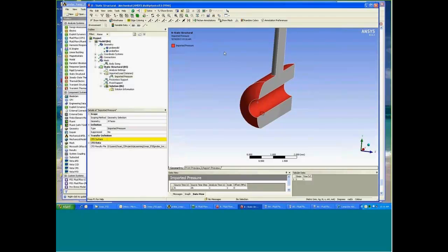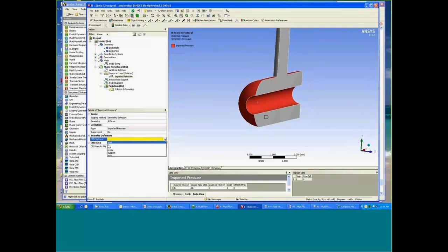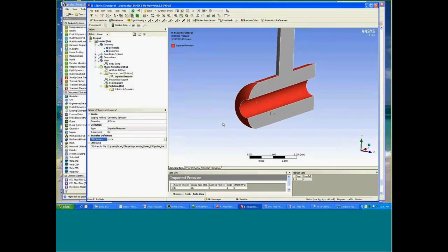which means I'm going to transfer fluid pressure from the CFD solution to mechanical, right? And I select the matching surface right here, right? And from the CFD boundary condition. That is the reason why we need to define these surfaces and provide name selections for these surfaces in the CFD analysis, to make sure I can pick the corresponding boundary condition or fluid load from the CFD side, and I use that to transfer to the mechanical system. After that is done, all I need to do is just click Import Load.